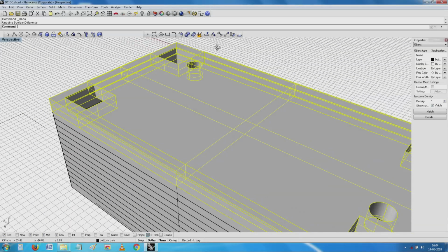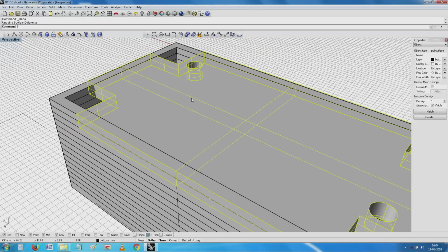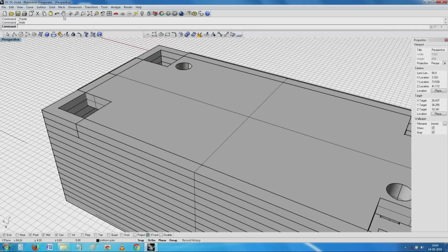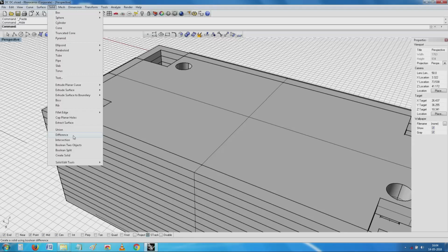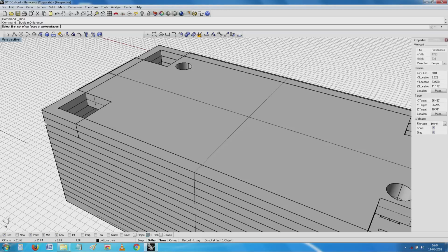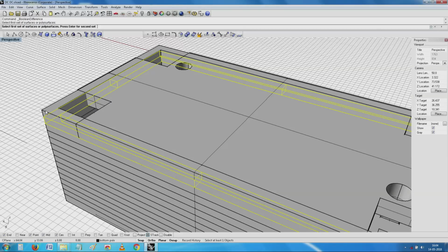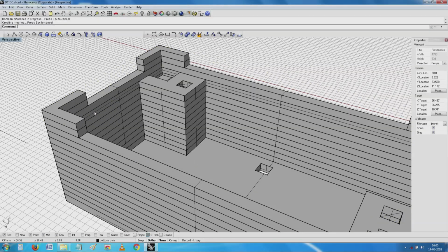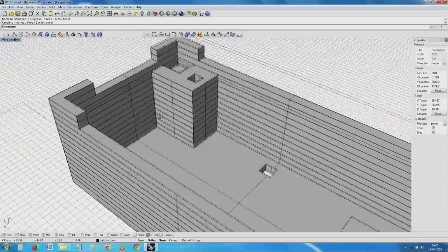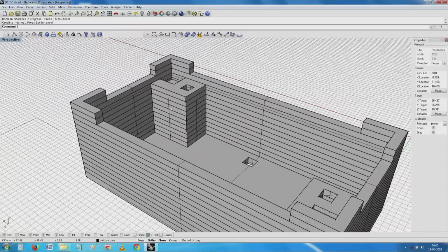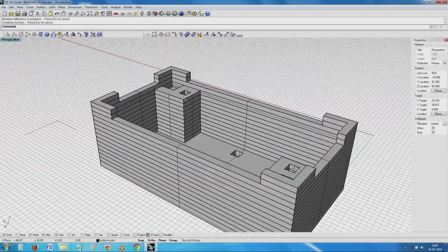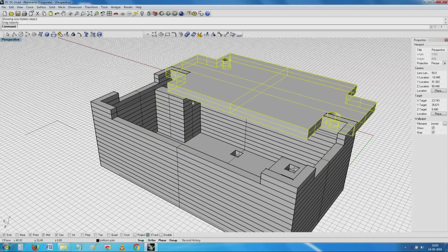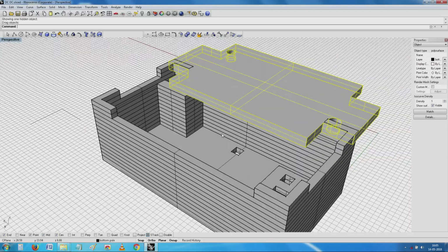Yes, in this I need to copy one object, hide it, so that I continue to have it. Now, do the Boolean with these things. See, now you will notice that I do have the object that I wanted to create, and in this case they also represent the various layers, and now I take this cover over, and the cover sits very comfortably here.